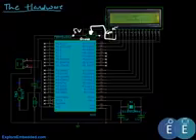Now one thing to point out here is, you set the contrast such that before you even burn the program on the controller, you ensure that you have all square boxes on the first line of the display. That sets the contrast, so you will not have to dump the program and not know what is happening. So first ensure that you get all the square blocks by setting the contrast on this pin.